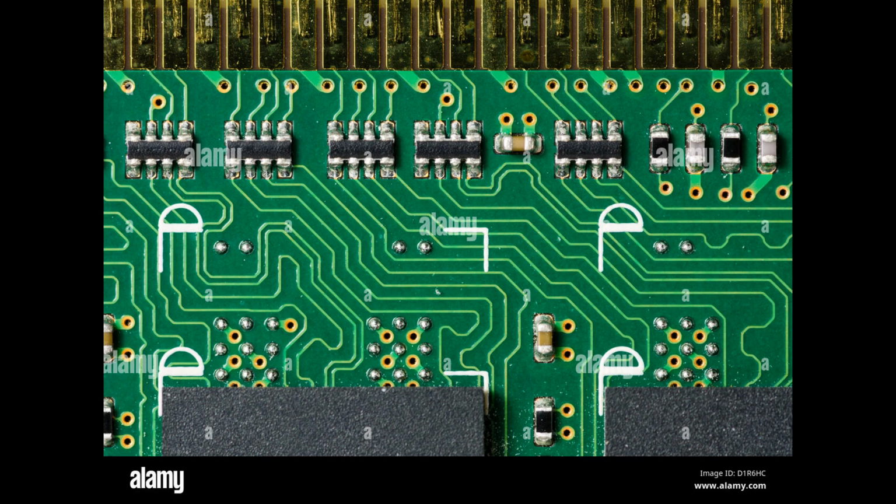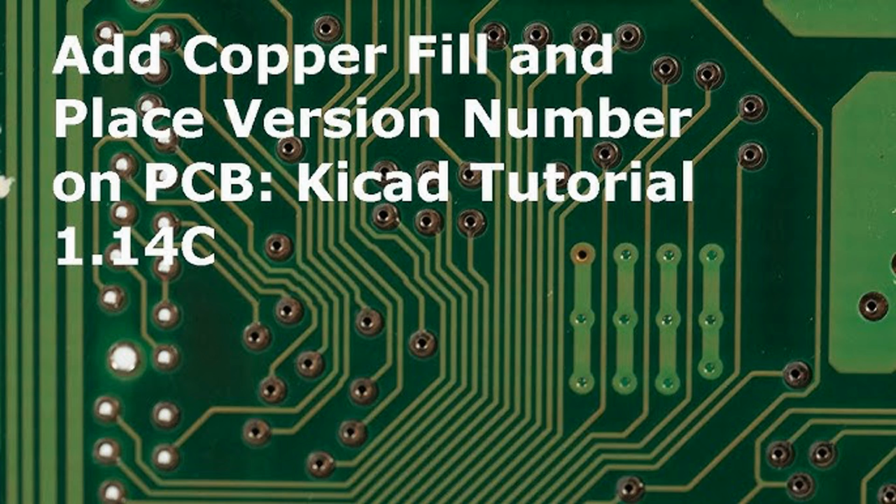They terminate at one of the inner layers and do not extend to the opposite side of the board. Buried vias are entirely contained within the inner layers of the PCB and do not connect to the outer layers. They are used to establish connections within multi-layer boards without affecting the external appearance of the PCB.